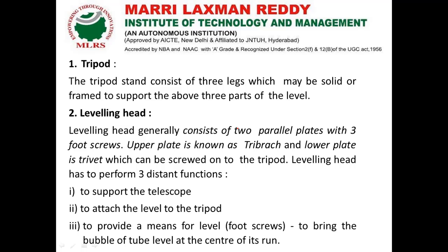So now we will discuss these components. The tripod stand consists of 3 legs which may be solid or framed to support the 3 parts of the level above. Next, the leveling head. The leveling head generally consists of 2 parallel plates with 3 foot screws.